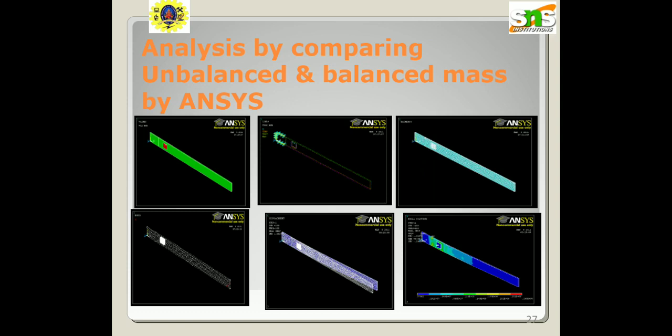And the next one is the tuned mass damper, introduced as a part of a suspension system by Renault Nissan. In the production of car companies, tuned mass dampers are widely used in crankshaft pulleys to control torsion vibration, and more rarely the bending modes of the crankshaft. They are also used on the driveline for gear whine and elsewhere for others.